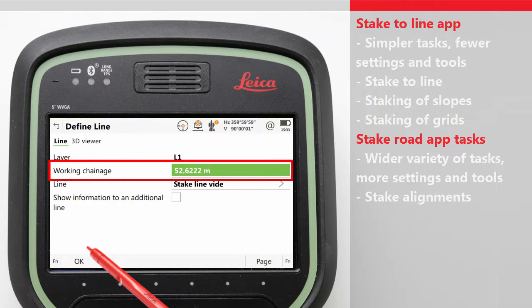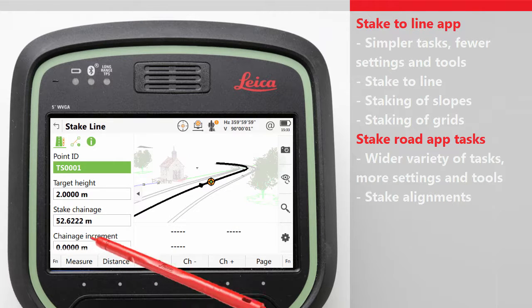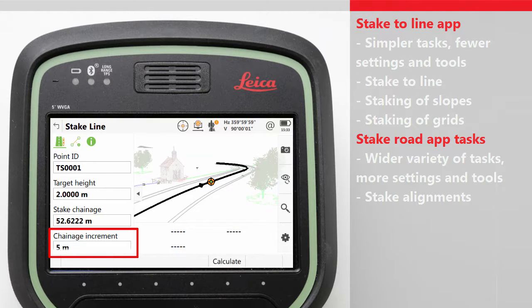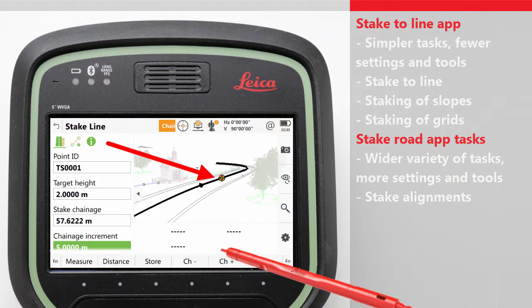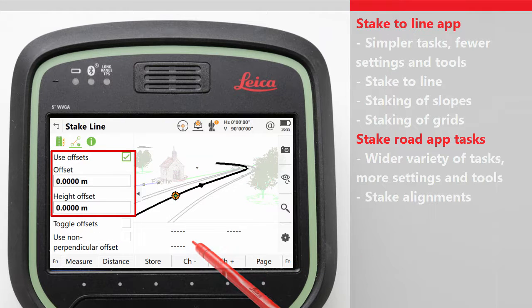Enter the chainage where it is wanted to start staking, and then you simply start staking. Within the stake panel, it is possible to enter a chainage increment. This allows you to easily move up and down the alignment. And it is also possible to enter a horizontal and vertical offset if needed. Again, the actual staking of the location is the same as within the How to Stake a Point video.